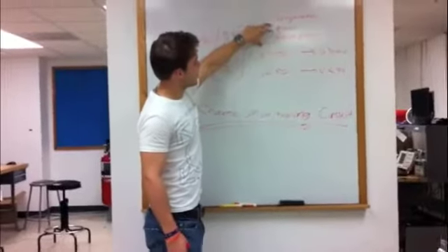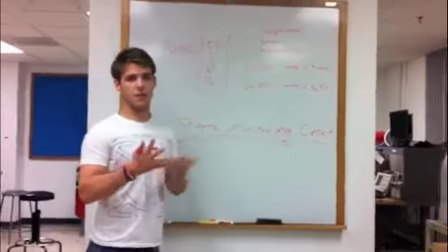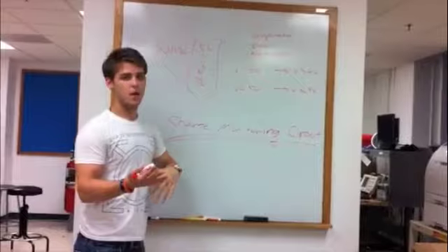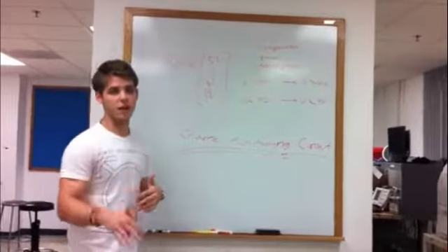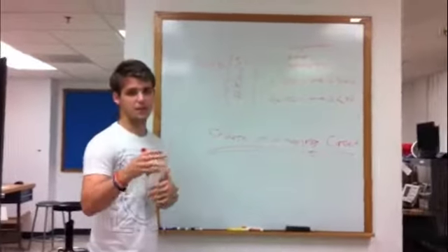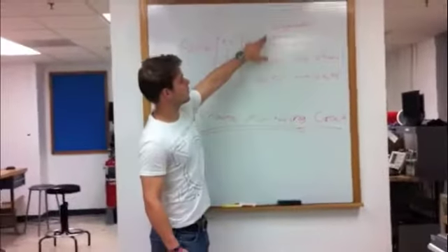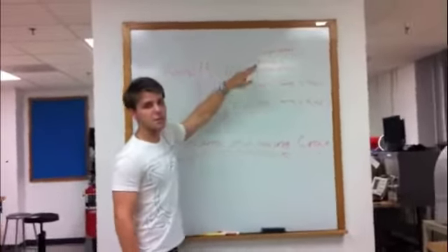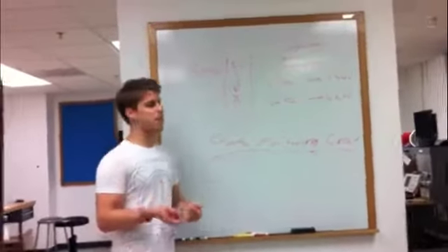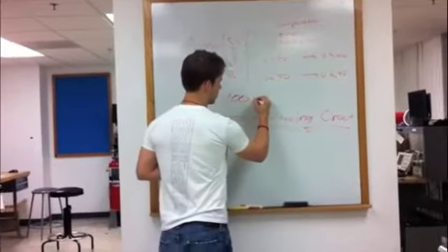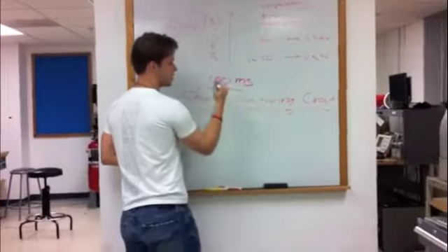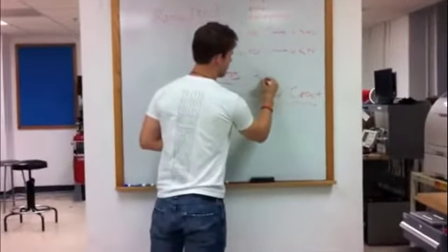We have a comparator and a transistor, which are the same ideas. They act as switches, or they turn on and off when the voltage has a certain value based on V plus and V minus. But the third thing that we introduced into this circuit is the timer. Part of our project was to have the LEDs flash at a certain point, at 100 milliseconds is how long the flash is, every 2 seconds.